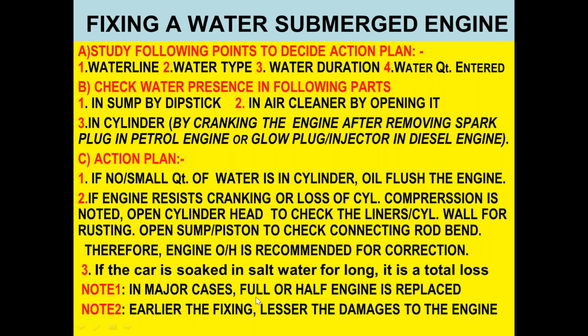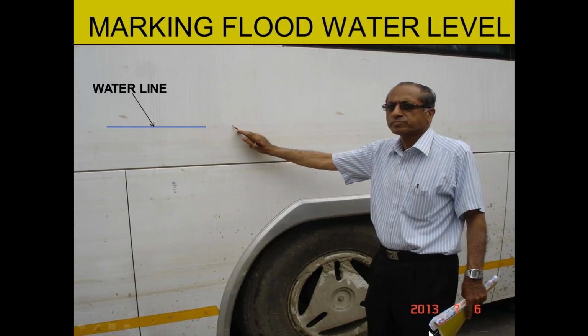Please note that in major cases, full or half engine is replaced, and the earlier the fixing, the lesser the damages to the engine. Marking flood water level. Here, one of the luxury buses I was surveying, the water was up to this level. So I made a line here, called the waterline. All the parts below this line were considered in my claim, and all the parts above this waterline were rejected by me.